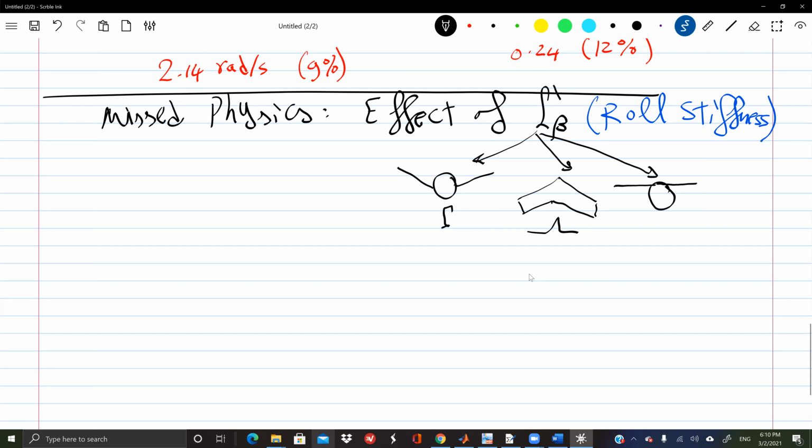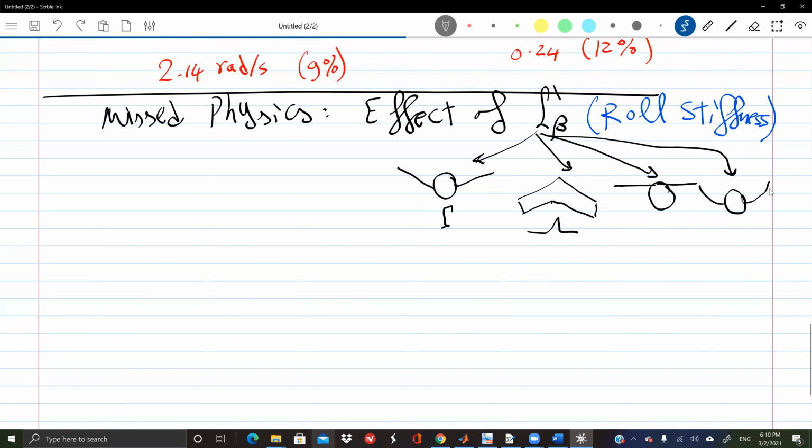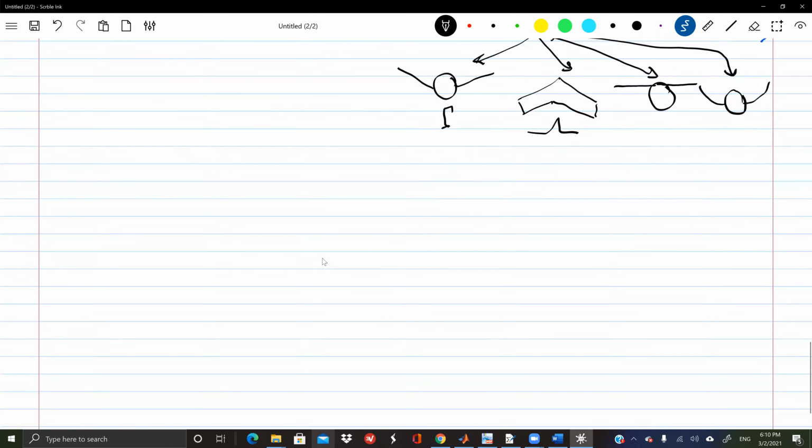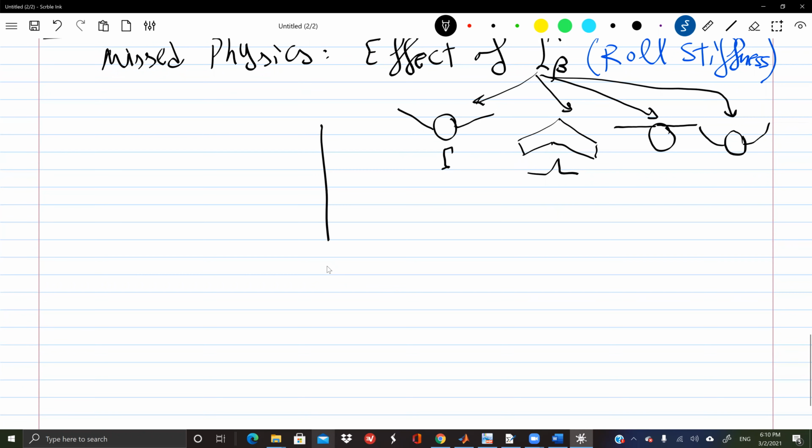There is one more source, which is the natural one. When you have the airplane, the wing is loaded by a lift distribution. It's just clamped at the root, so it acts like a cantilever beam. So it bends up like this. And this is inevitable. It's unavoidable. It's just the natural response of the wing. And you can see it looks like a dihedral, just a curved dihedral. So it gives you more negative L beta. So all of these factors increase your L beta much. And let's see what's the effect of increasing L beta on the Dutch roll mode that is neglected by the approximation. So again, this is the real axis, this is the imaginary axis.